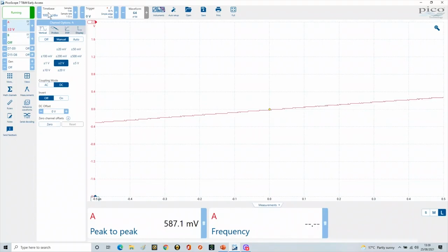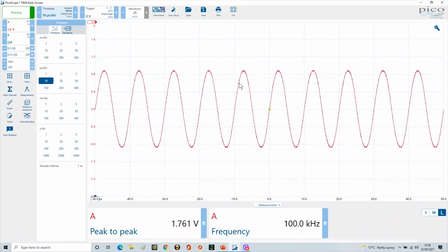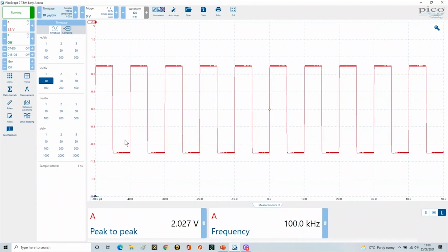Okay, and we're just going to bring the time base in so we can actually see this. There we go. I want to change this to a square wave, so bear with me whilst I change the waveform. That's looking great. We've got a square wave there. Everything's fine at the moment, because from a frequency domain view we're only running at 100 kilohertz, so the odd harmonics will be 300 kilohertz, 500 kilohertz, etc., and the scope probe is actually able to see those.